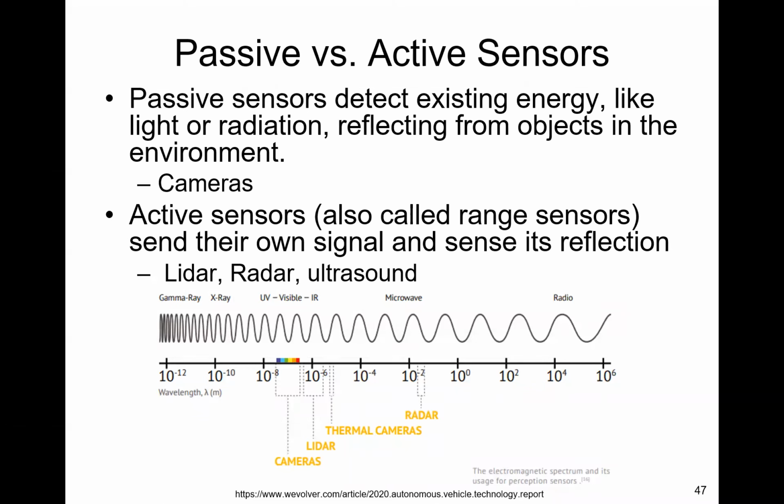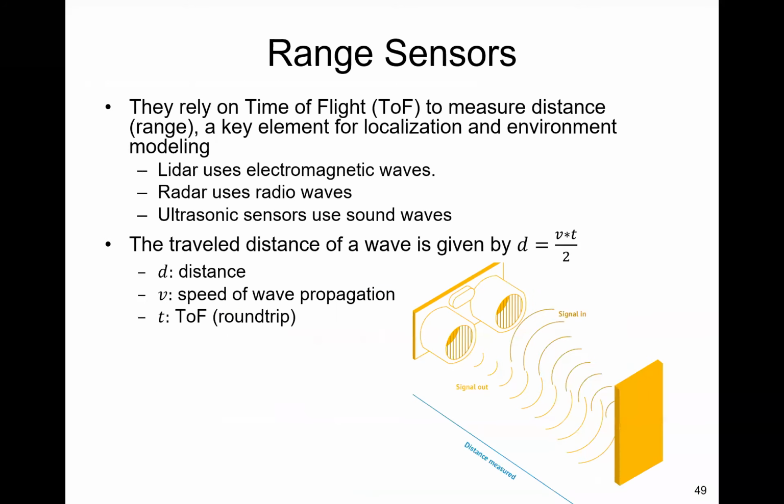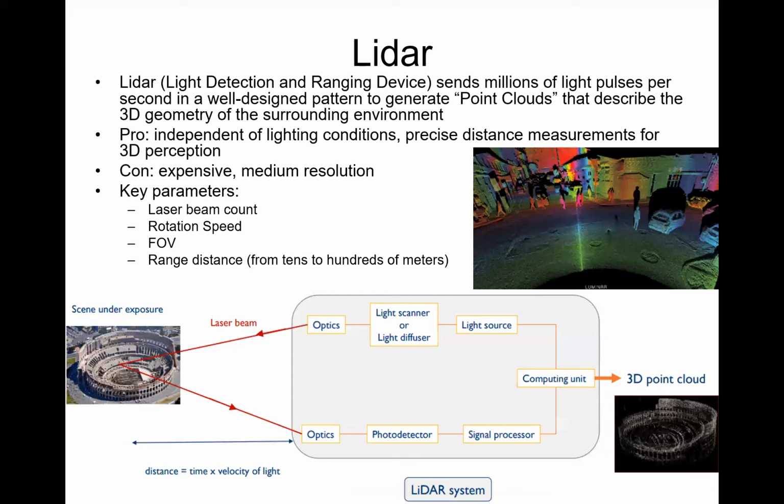So it is a laser then? Yeah, it is a laser. Lidar is laser. Okay. And one more question would be that when Lidar has sent the laser beam, how does it recognize what is returned? So how does it correlate that? It doesn't. All it returns is a bunch of points, a point cloud. So every laser beam hits the object and you get back a point. The point has no color, no other information, no pixel. It's just a single point that something is there. And then you get millions of points from a LiDAR scan.